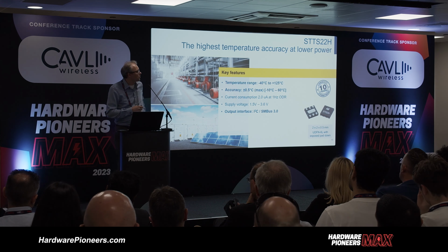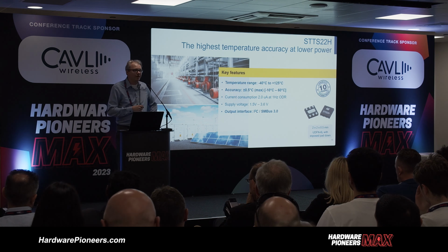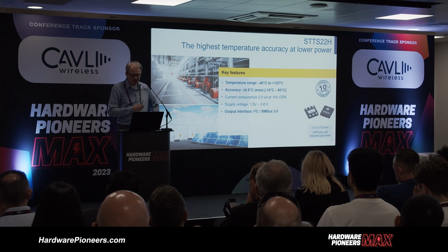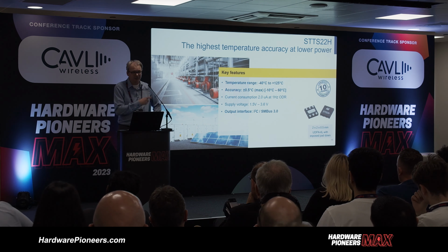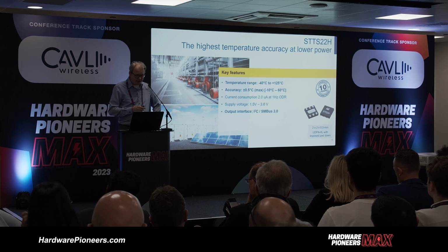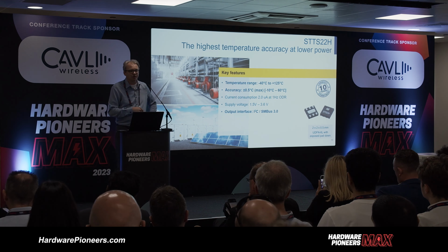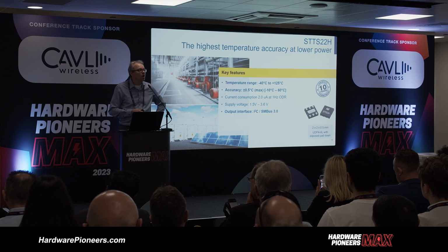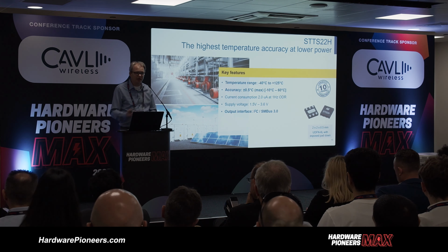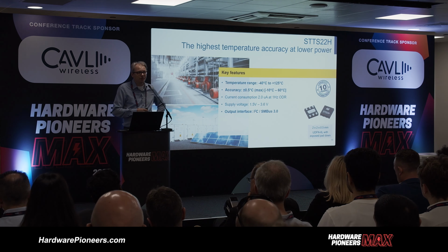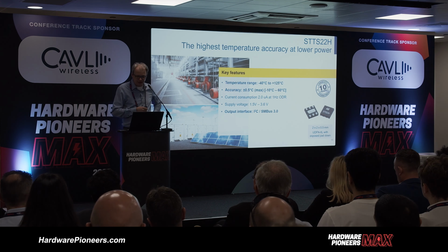And then one example of a very common, maybe even the most important parameter to measure is temperature. And even this is a brand new sensor. The new thing here is that it measures the temperature from this pad in here. Again, it simplifies making the total product when you just guide the heat into this pad, and you can make the temperature measurement with very low latency, and this way catch the failure. So this would be the exact model proposed for this type of use case.